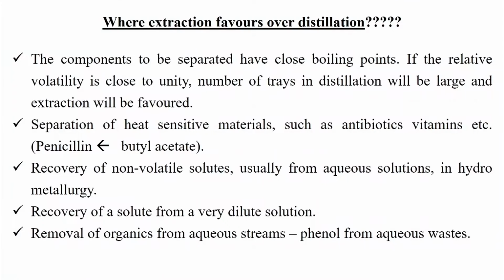Sometimes recovery of non-volatile solutes, usually from aqueous solutions in hydrometallurgy, is done by the extraction process. For a very dilute solution, we cannot separate using distillation or other processes, but the extraction process can efficiently separate the target components from the dilute solution. Some removal of organics from aqueous streams, like phenols from aqueous wastes, is also done by extraction, where it cannot be separated by distillation.